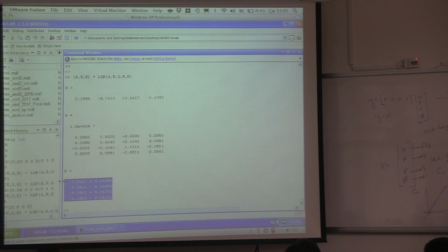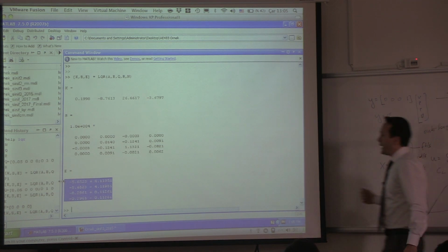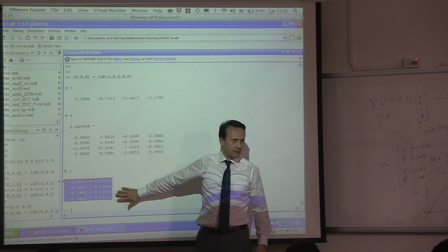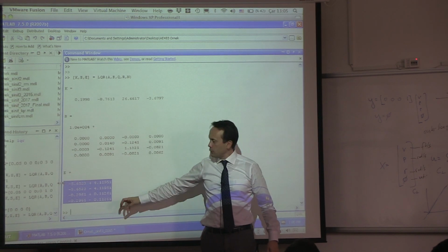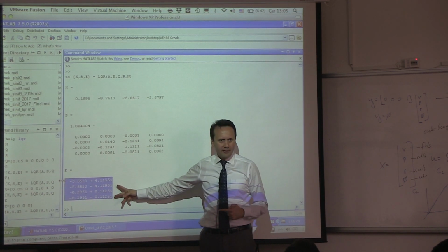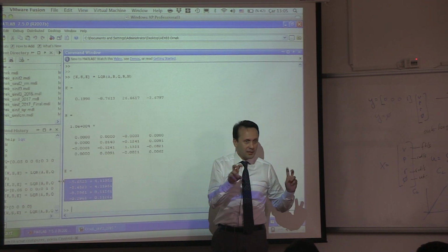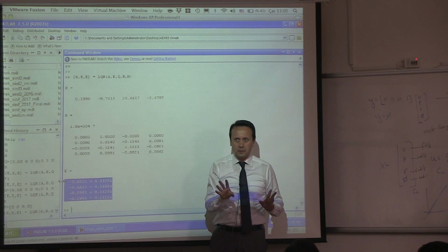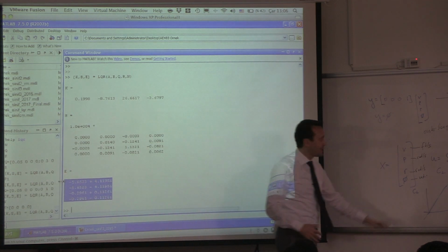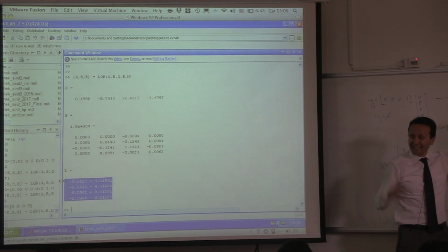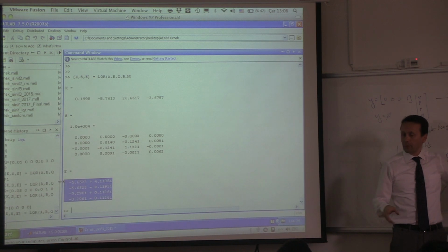It says if you use these optimization weights, then the eigenvalues shall be here, right? Now you can use these desired eigenvalues in the integral problem as the desired eigenvalues. Do you understand that? Okay, so the desired eigenvalues are now dictated from the LQR problem.